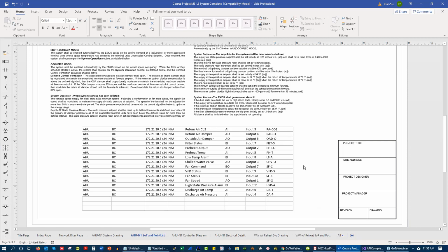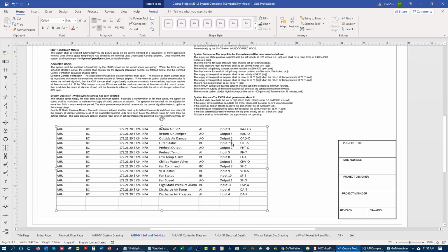You check the sensed value on your controller, front end, whatever, and then the actual value you're seeing there in the field on your meter or thermometer. And that is how you do a basic point-to-point check.